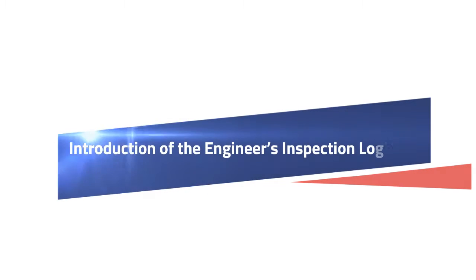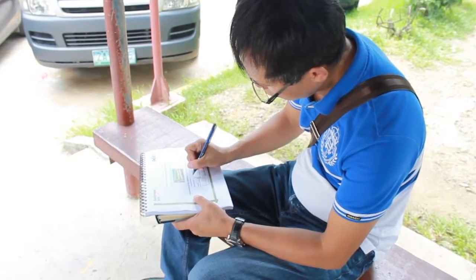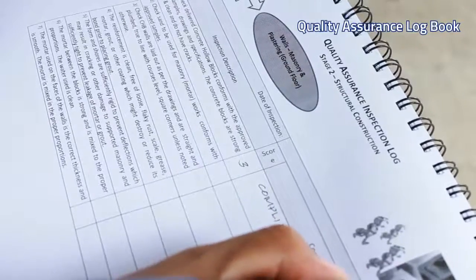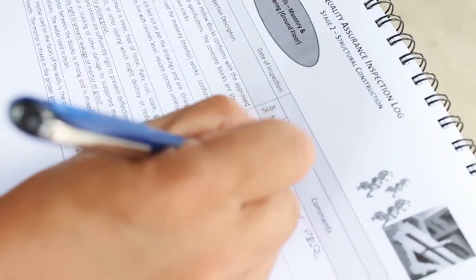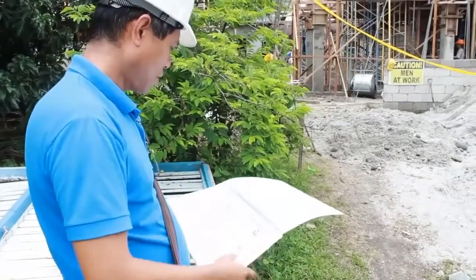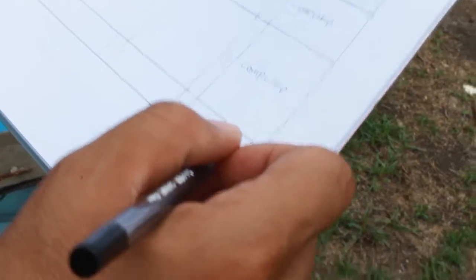Introduction of the engineer's inspection logbook. The engineer should record his or her observations in the QA logbook, together also with the details of any discussions or agreements made with the contractor in terms of issues that need to be addressed. At every site inspection visit, the engineer must record observations and details in a Quality Assurance Logbook, or QA logbook for short.